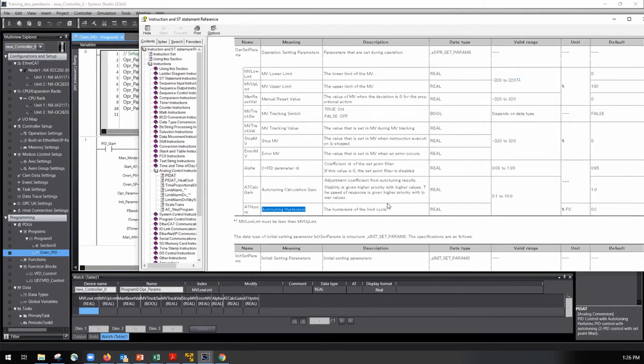So what our deadband does is it gives a window where the PID loop will ignore a slight variation, and that just helps stop tiny little bits of chatter and constantly throttling a valve or throttling a motor up and down. So I'm going to stick with the default recommendation here of 0.2, and this one is again a percentage of our output, so keep that in mind.